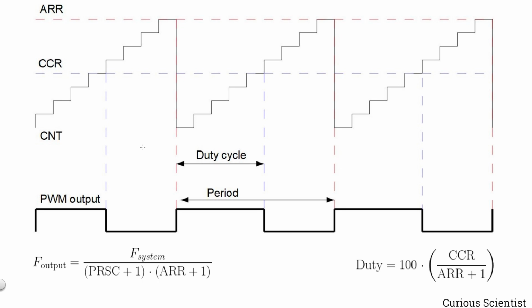And then to keep track of the counter, we can use the CNT register value. So for example, when we start the counter, we can check the value of the CNT, and based on the counter's frequency or period, we can determine how much time elapsed.